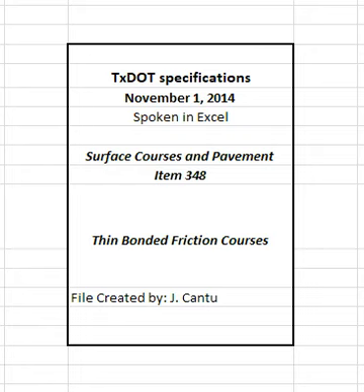If department-owned RAP is available for the contractor's use, the contractor may use contractor-owned fractionated RAP and replace it with an equal quantity of department-owned RAP. Unfractionated RAP is not allowed in PFC mixtures. Department-owned RAP generated through required work on the contract is available for the contractor's use when shown on the plans.